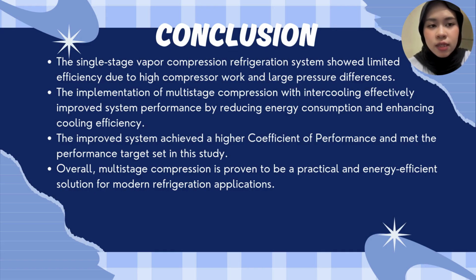First, the single-stage vapor compression refrigeration system shows limited efficiency due to high compressor work and large pressure difference. The implementation of multi-stage compression with intercooling effectively improves system performance by reducing energy consumption and enhancing cooling efficiency.